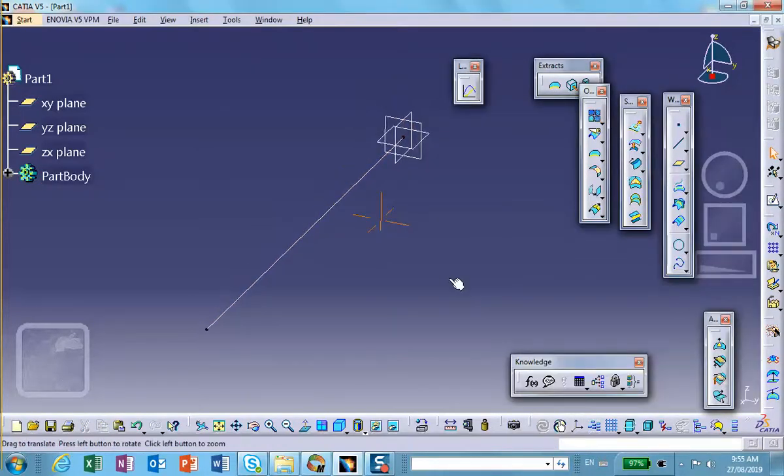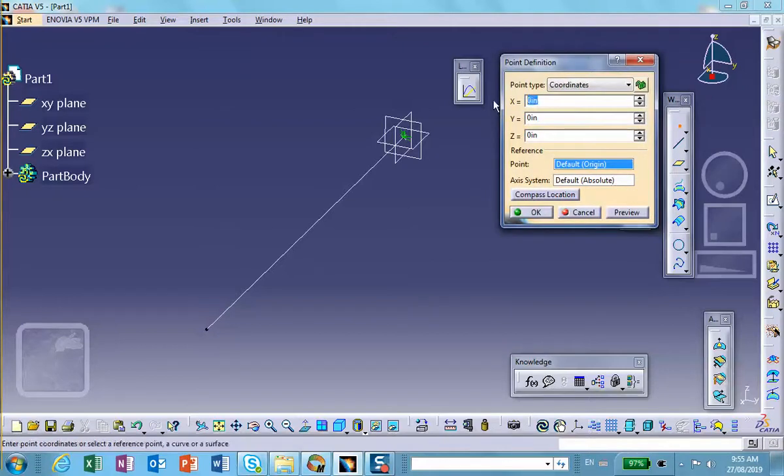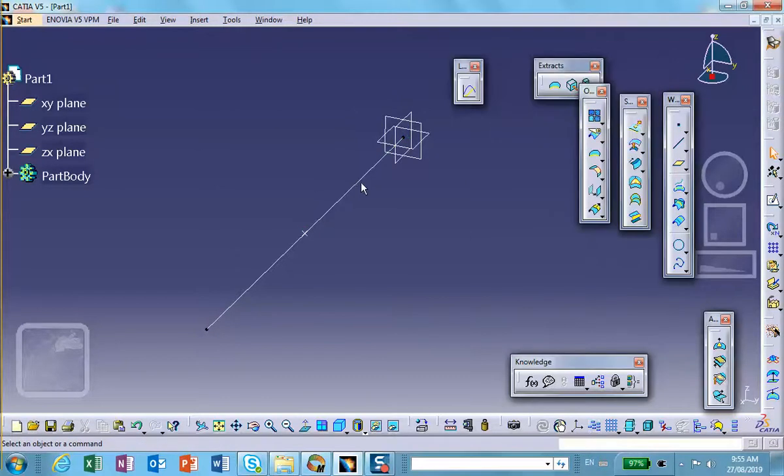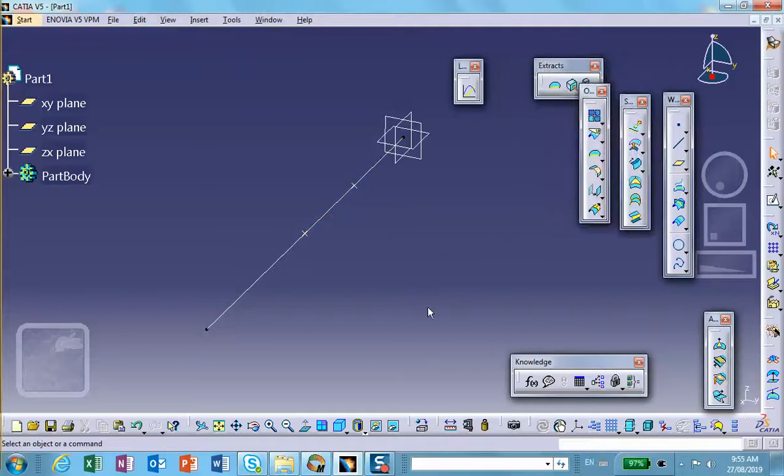No problem. Now, I'm going to create 2 points. One of them is exactly at the midspan. This is where monitoring is going to be done. So that's 10 inches. And the other one has 5 inch location where the load is going to be applied. Okay, good. So let's make this thing out of steel.